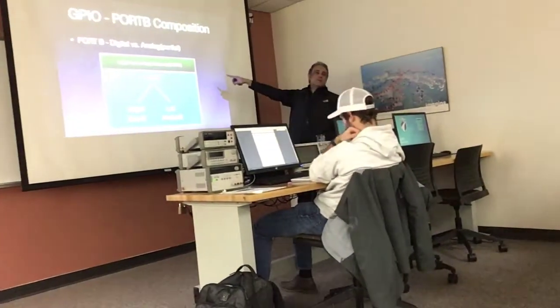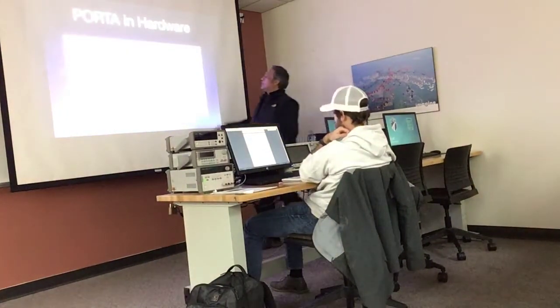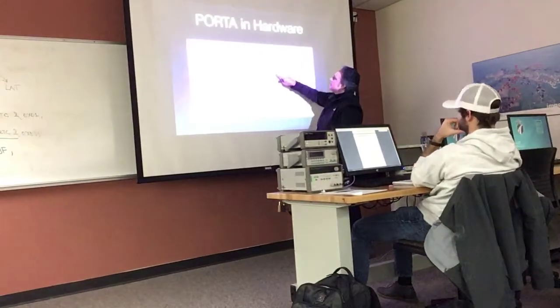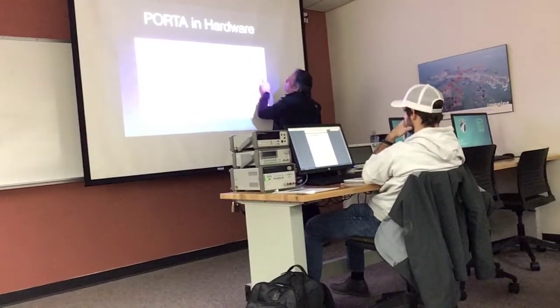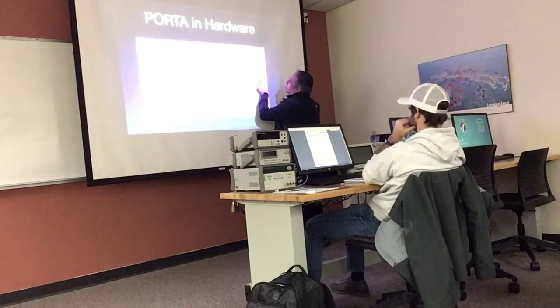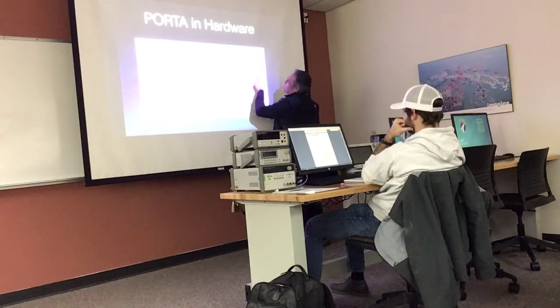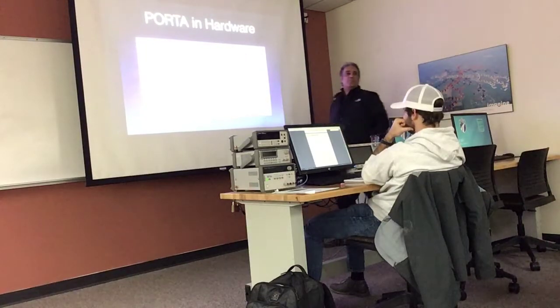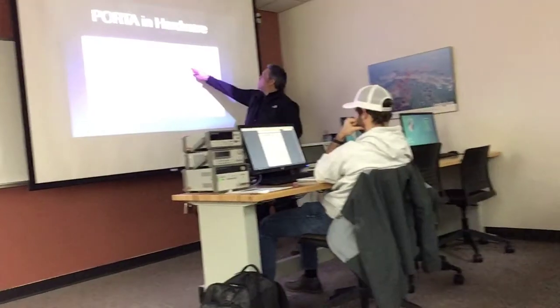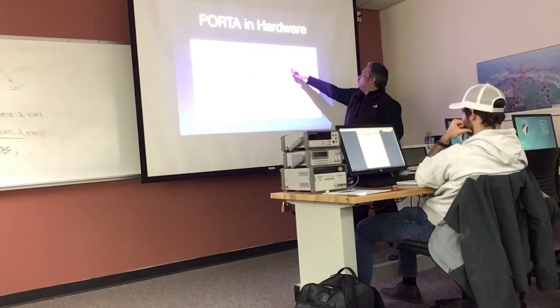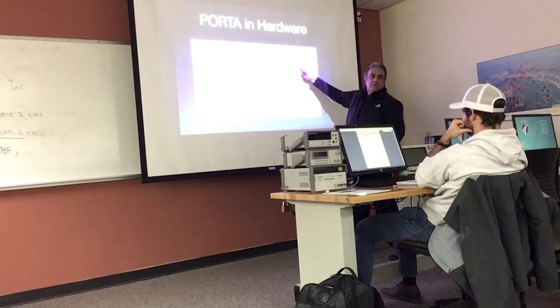Port B contains a whole bunch of analog stuff. Let me show you. Here's port B. Port B is on the top pins from 33 to 40. Here's the B's. They're all together. But look at the A's. Some of them have analog in it. So analog 8, 9, 10, 11, and 12 are located inside of port B. See that? So if you want to use B2 as a digital input, you're going to have to shut down the analog version of it.